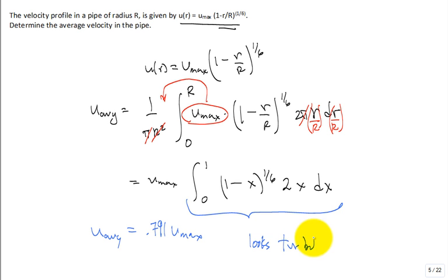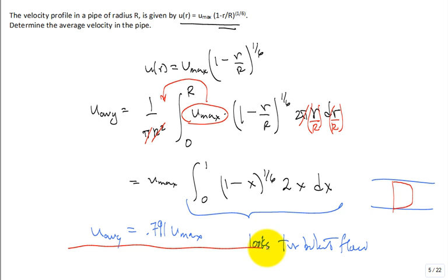This looks like turbulent flow. The profile is relatively flat in the middle. What does quadratic look like? Parabolic. It's much faster in the center. So what was the contrast if it was laminar? U average equal to what times U max? 1/2. True? Okay.